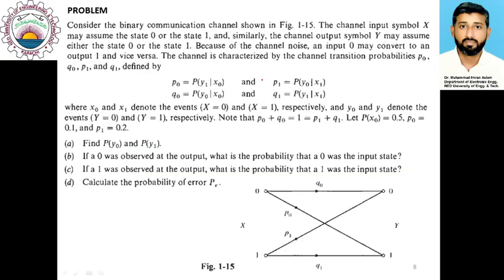So this is the overall situation here. I just described the probabilities associated with these transmissions. These probabilities are sometimes named channel transition probabilities, because they show how the symbols will experience the transition when they pass through that particular channel.